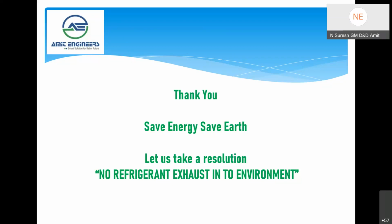Say, for example, if we want to change the filter dryer or any line component, if the system is working okay, we can recover the refrigerant and reuse it. There are equipments available. We can recover the refrigerant, recycle, and reuse the same refrigerant. In cumulative, we could save that much refrigerant as well as the environment. We will not be putting this gas in the atmosphere.